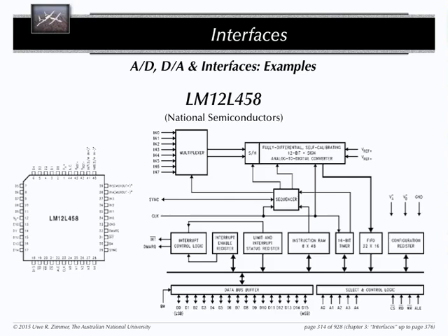That's the first hint where you see that it looks like memory, but it doesn't behave necessarily like you expect memory to behave. You're not used to the fact that reading from memory is side effecting. You expect reading from memory, you can do the same thing 5 times and you read the same value 5 times. That's not true on hardware devices. Not necessarily true, at least.